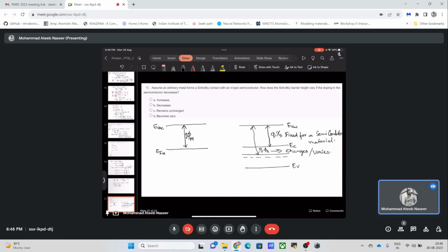So we will be having this Schottky or ohmic contact accordingly, depending on the condition on the metal work function and the semiconductor work function, and the conditions on, for example, the doping levels as well. So it would try to influence the slope of this conduction band edge near the interface. If we dope the material more, the edge will be sharper.